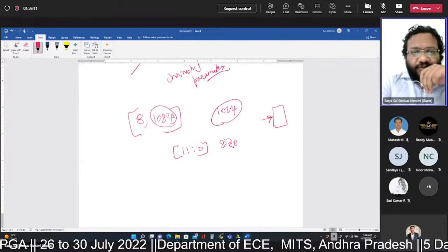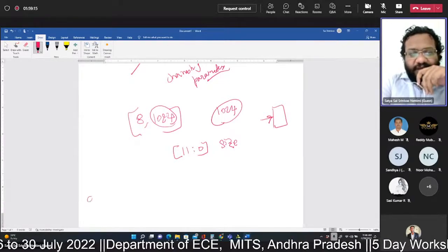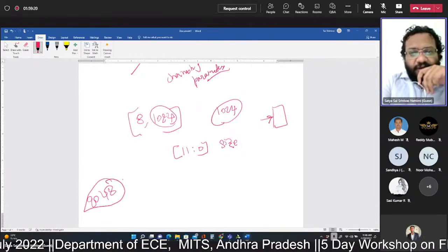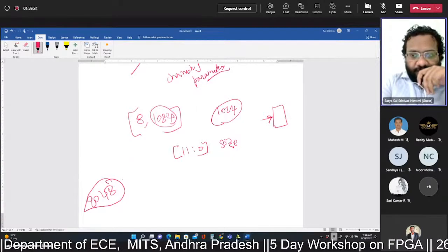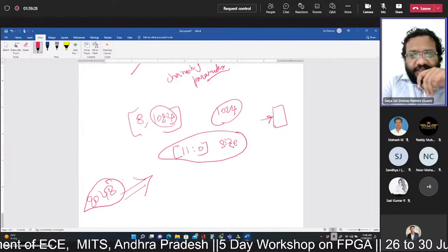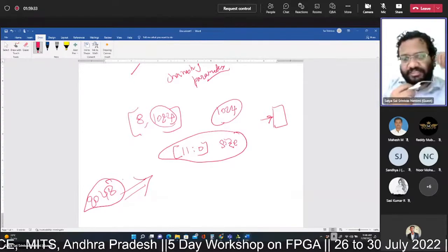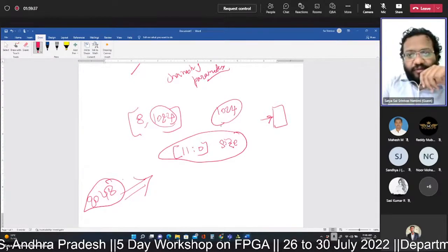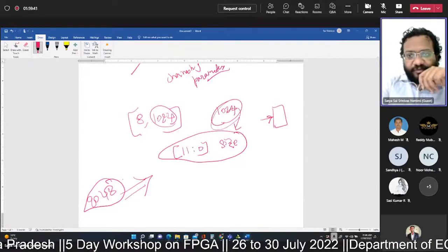Now if I ask you to evaluate the energy of a signal that has samples up to 2048, the underlying concept remains the same, but what you have to change is the size of the parameter. Why? Because earlier you designed your HDL description by hardwiring it to meet the requirement of 10 bits to represent the size of 1024.